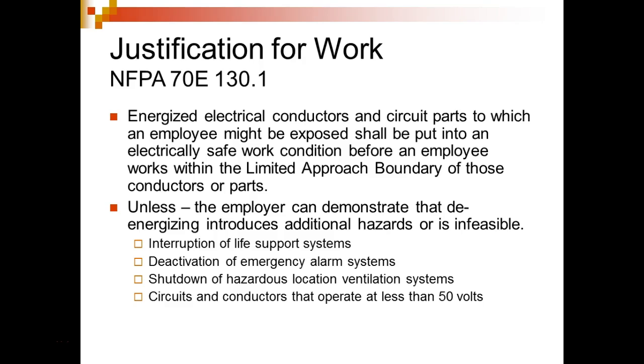And other people don't understand that meters have resistance. So they're not infinite resistance. You need to understand that too. But 10 megohms is a lot, right? You understand? But if I got into 1,000,000 volts, 100 megohms, the meter would blow up, right? You understand? Because it's pushing current through resistance, right?